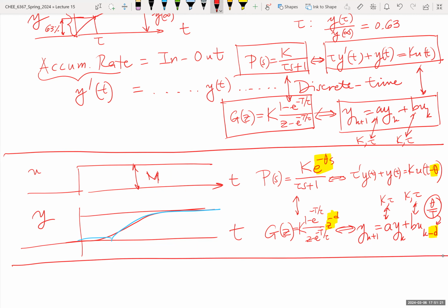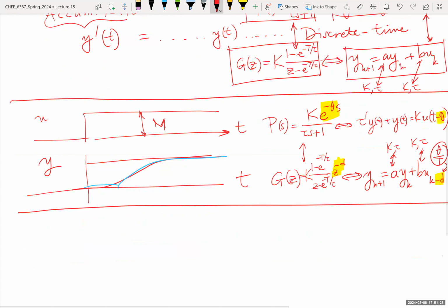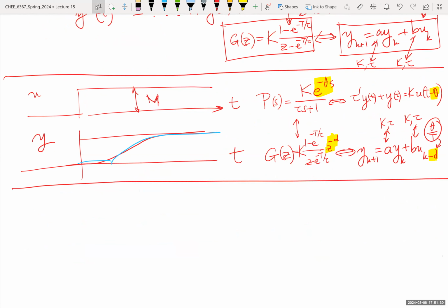Continuing the notes in section 1.2 on page 5, I talk about second order models. The second order model is one which may have a second order transfer function or a second order differential equation. And again, in the response of that system, we typically distinguish two cases. One is when we have a system that is called overdamped. This is jargon borrowed from mechanical engineers.